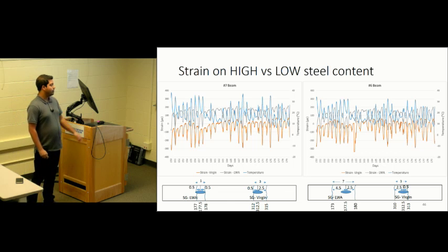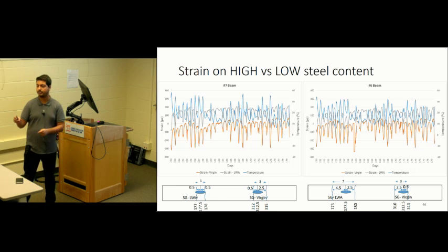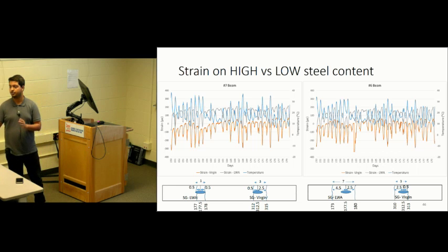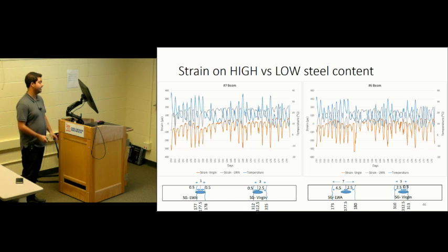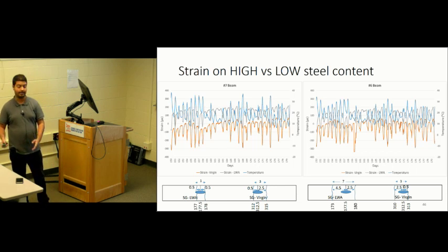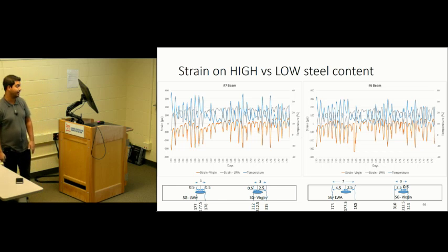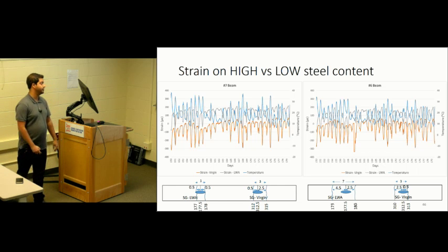If we go up to 180 days, the effective slab length, or the distance from the strain gauge to the crack, reduces drastically, down to around 7 feet or even 1 foot. That means the small section moves more, so we start seeing more variation in strain over time from the strain gauge.